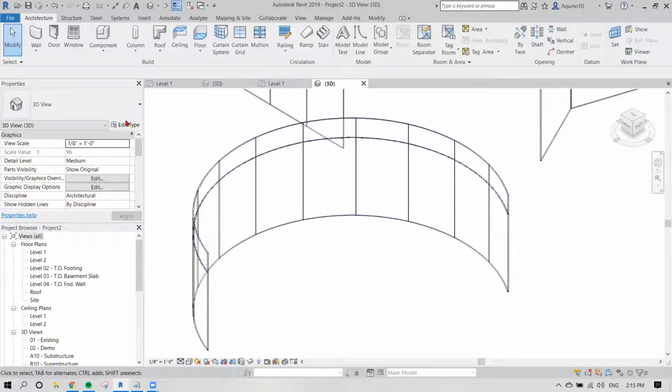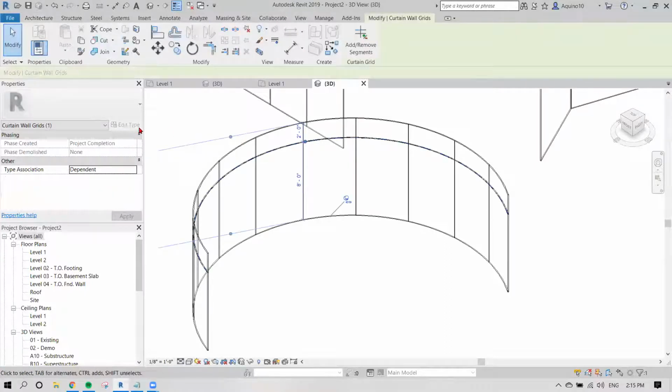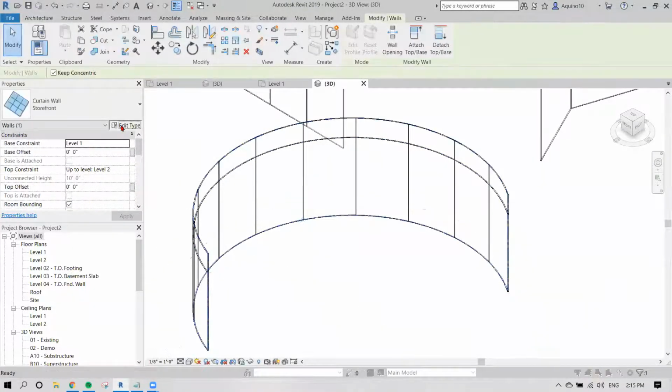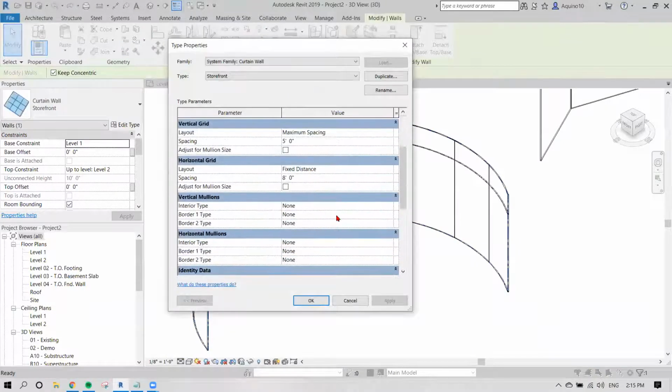But that doesn't apply to our mullions. So right now I'm going to introduce mullions. We have some drop downs and not too many options: circular mullion, rectangular mullion, it doesn't really matter. I'll select one for both the vertical and the horizontal section.